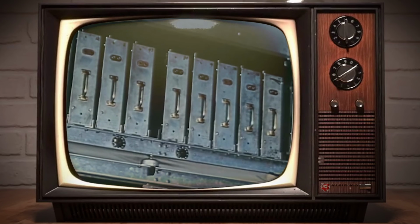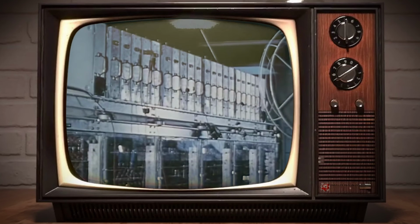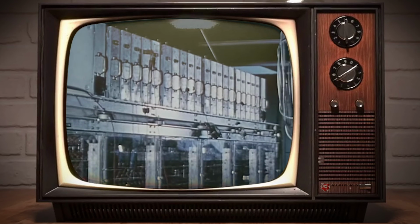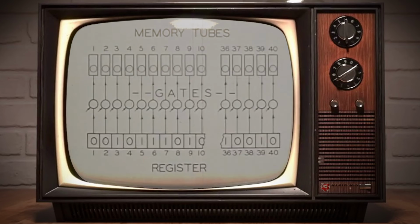The problem is next transferred from the register to the memory. The MANIAC's principal memory is of the electrostatic type, utilizing 40 standard 2-inch cathode ray tubes, mounted in individual metal cases above the arithmetic unit, 20 at the front and 20 at the rear. A tape can be designed to write almost anything in the memory.